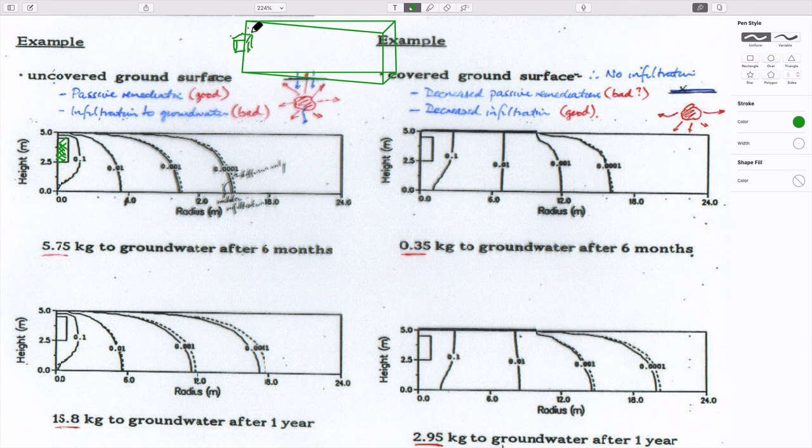And so if you look at the migration of the vaporized contaminants as it goes through here, both by diffusion like this, by the sinking of the vapors, which are denser than the air that's in the pore space itself, but also add to that effect the influence of rainwater washing down through this and carrying this portion down to this.